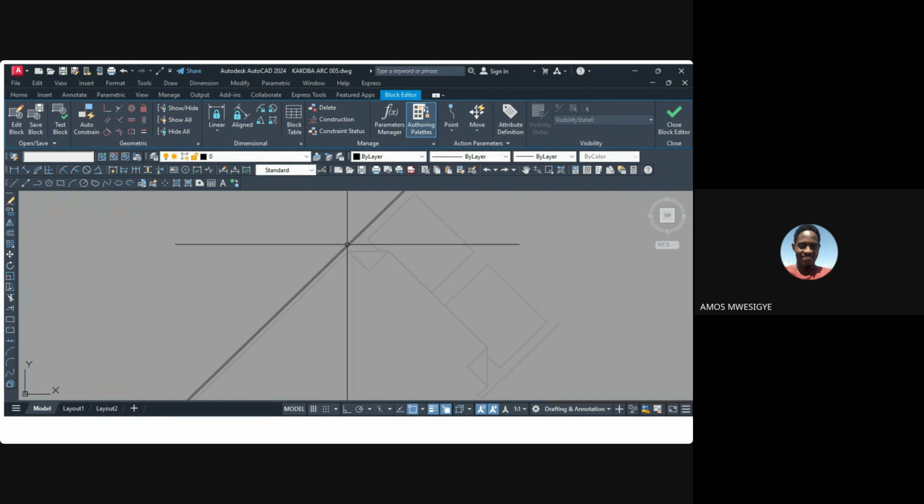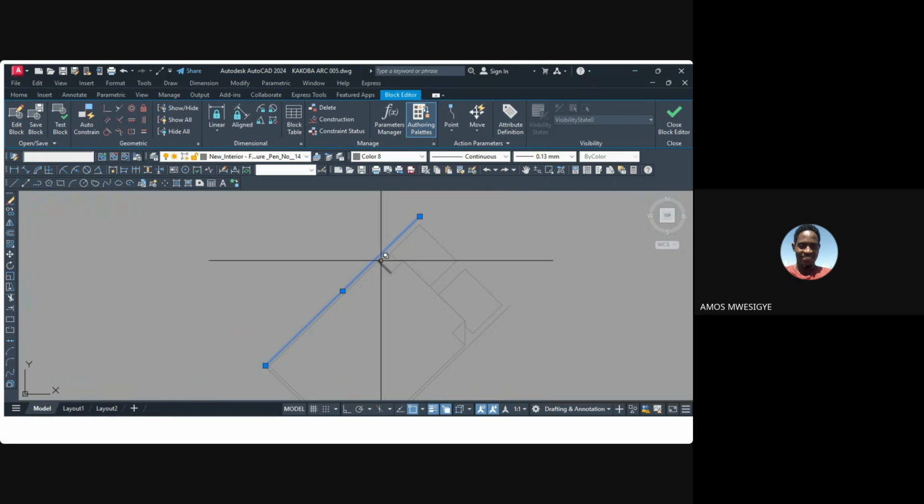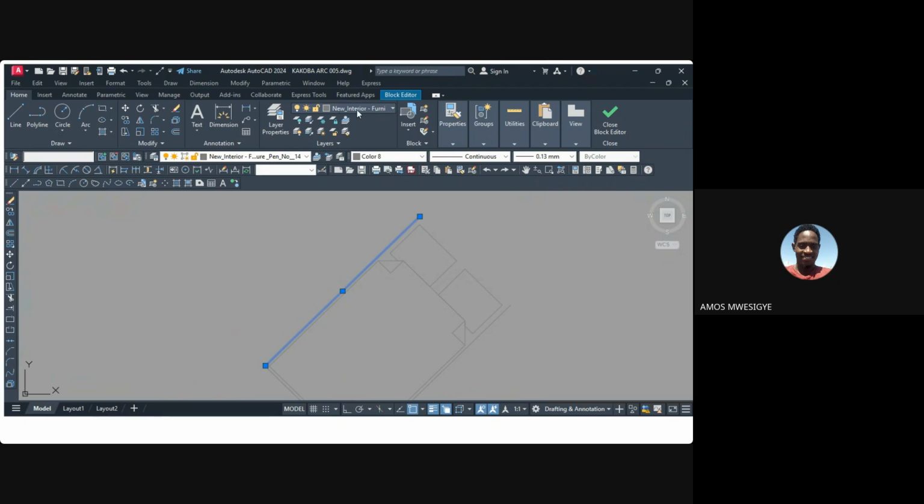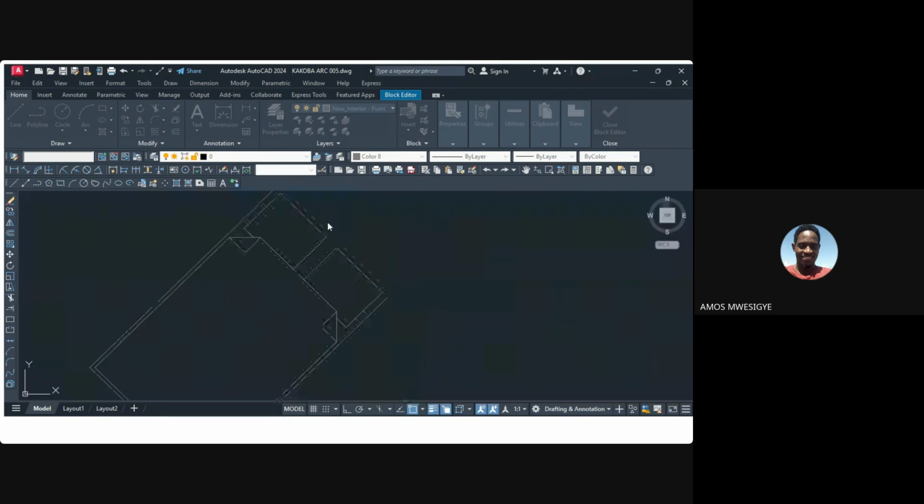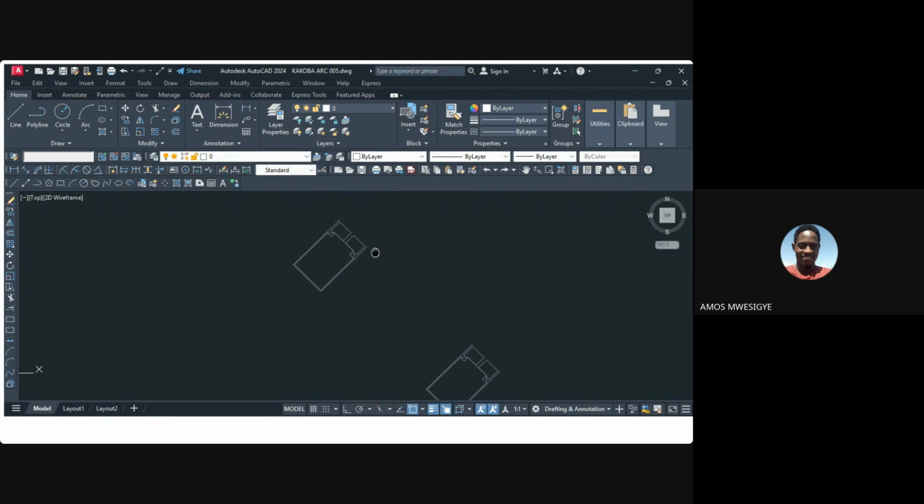So you would see here within the block items. If I select this item and come to home, you'd find that layer inside that block. Yet we put this block to layer 0. So that's the only reason why we have to explode to the minimum. We explode multiple times so that we get that individual item.